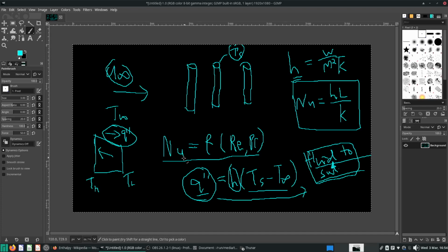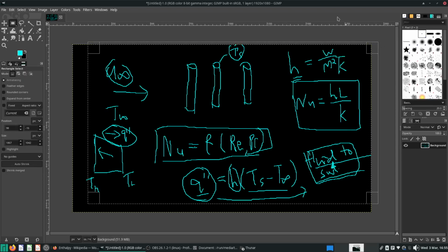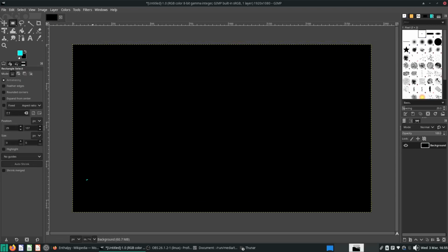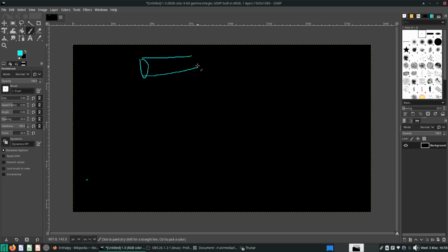For normal heat transfer situations, you have a lot of these correlations, which give you an averaged heat transfer coefficient. Even for a fluid flowing through a tube, most of the time you have some Nusselt number correlation that can give you a rough number for the heat transfer coefficient. This does give us a good estimate of what the heat transfer coefficient is.